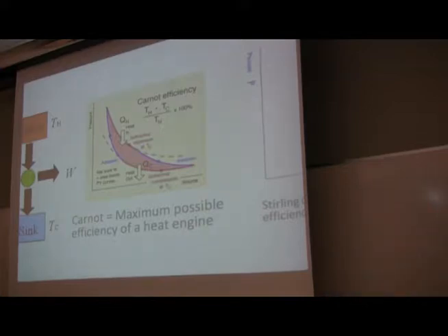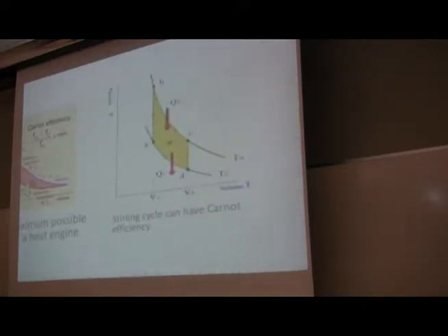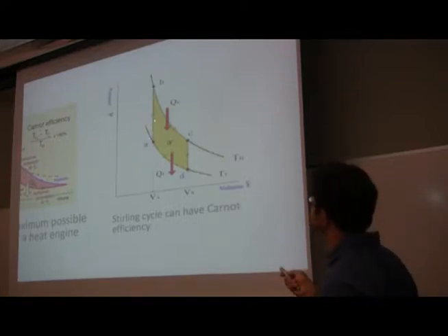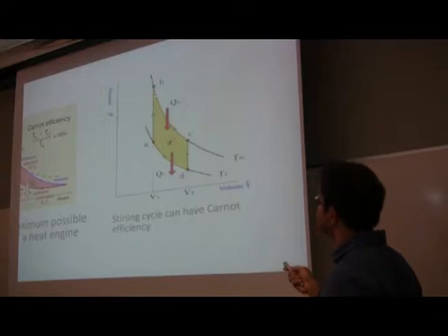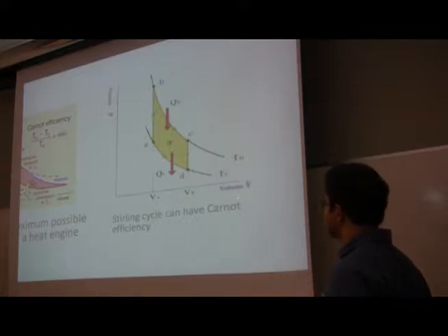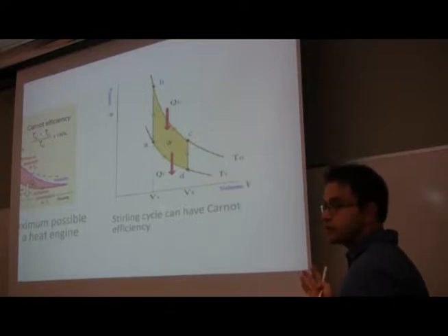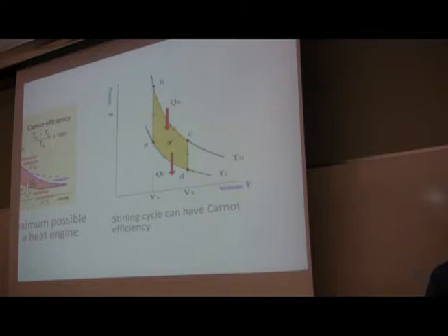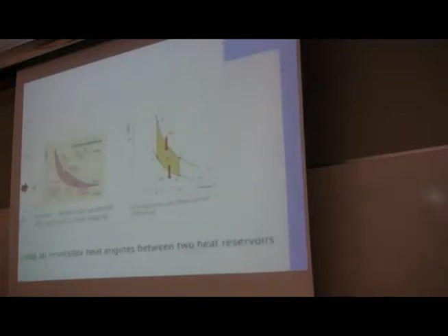The Stirling cycle, again, you don't need to know the details, looks a little bit different because you get these constant volume changes in pressure. So the only difference between that and that is that you can get these constant changes. And in theory, you can have Stirling cycles that can reach the Carnot efficiencies, but in practice, typically they don't. Obviously, all of these are theoretical, right? In a real engine, you never get to these kinds of efficiencies. It's useful to understand where the limits come from.